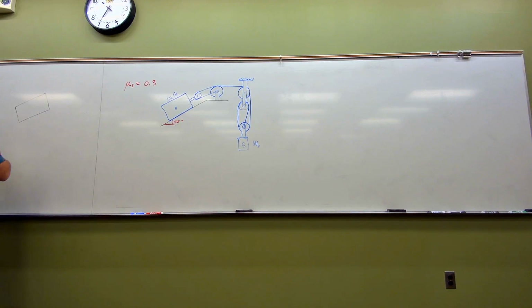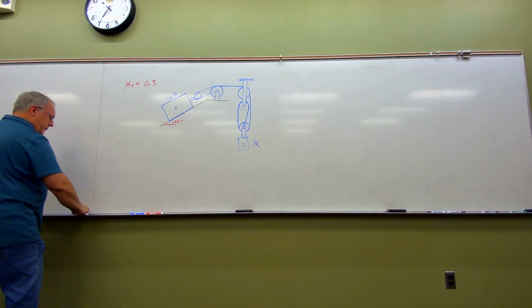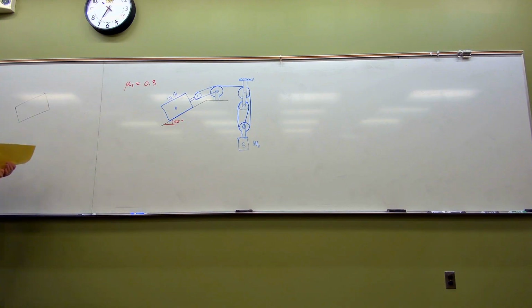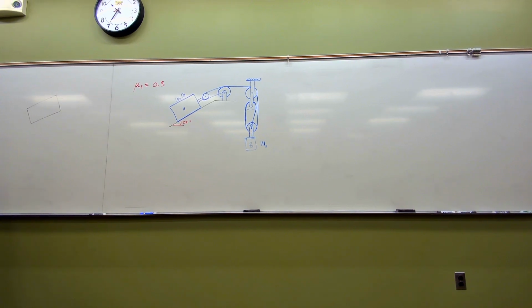So we know that this box here has a weight of 100 pounds. We also know, even though we weren't told this, we don't know anything about its dimensions, so we're going to have to assume it's a uniform crate. So uniform rectangle, therefore the weight has got to pass through the centroid of this. Centroid in this case would be the geometric center of the box.